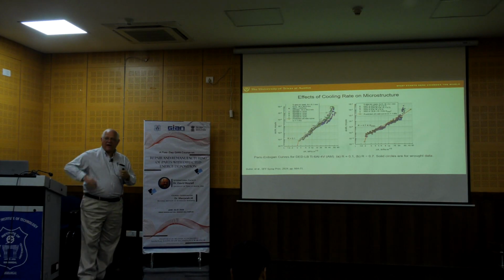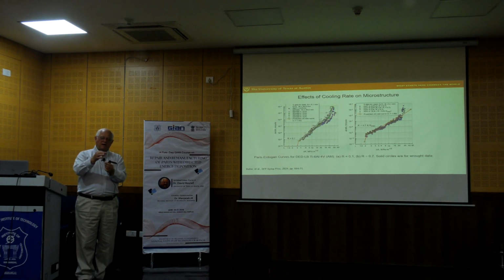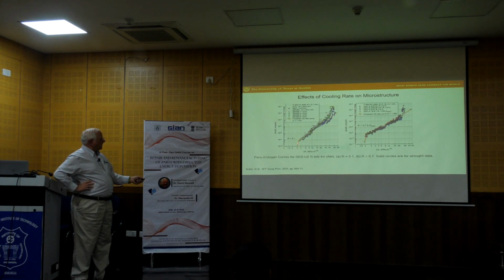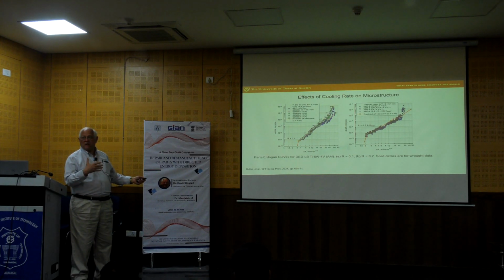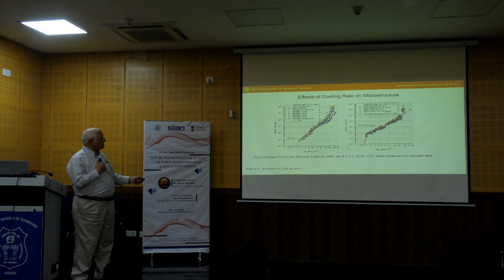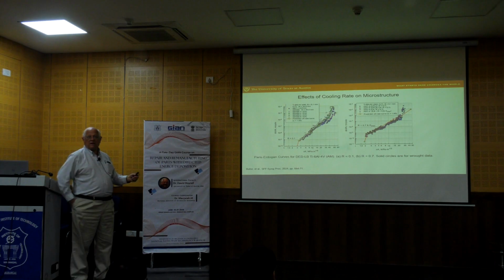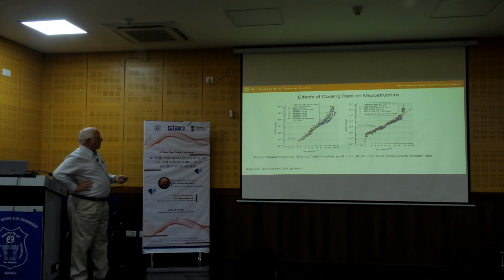So effectively, as I'm cycling the part during the test, and the crack is growing, on this plot we start down here at a fairly low stress amplitude, and the crack's not moving very much per cycle. But as the test progresses and the crack grows, we move up this curve, and towards the end, what we have is a very high change in stress amplitude, and the crack is growing very, very rapidly in one cycle. And so that's what these plots show.